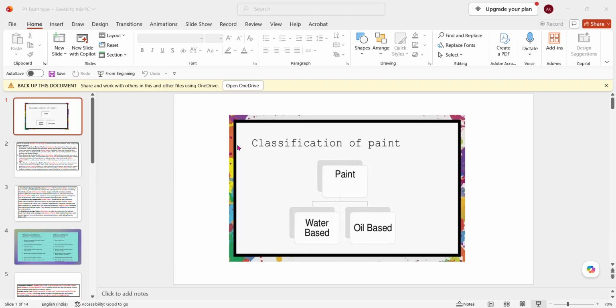It is not water based, and it is not oil based either. Main difference between epoxy paint and normal paint: epoxy sticks to the concrete and the metal. Normal paint is not able to stick to concrete for a long period of time. However, with epoxy, it is good to go because of properties like durability, toughness, corrosion resistance, but it takes 72 hours to cure, whereas normal paints take only 12 to 16 hours to cure.